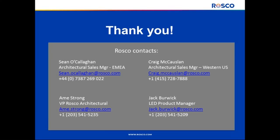Are there any others? I'd encourage anyone to send any others in. There's one query. I'm not sure I understand this. If a customer needs a specific size pre-soldered, can you provide this? Custom length, I presume it is. Yes, we can. It's very common for people to design a lighting scheme where they're going to require a number of less than 5-meter lengths of tape, and we can provide those with the pre-soldered connectors. And in some cases, if you want to connect multiples of those shorter than 5-meter lengths, as long as the total does not exceed 5 meters, we can actually include the mating connectors so you can piggyback those together.